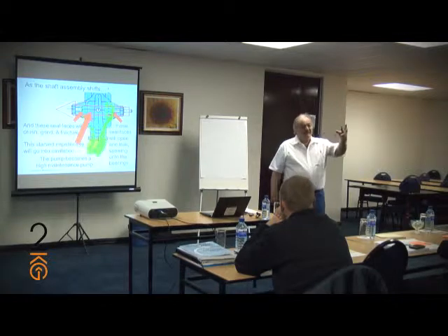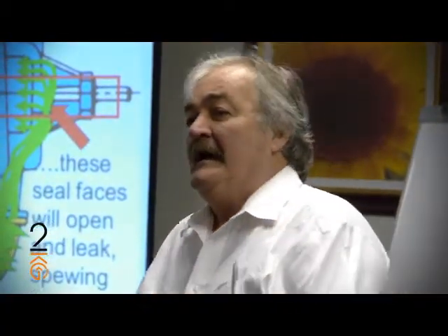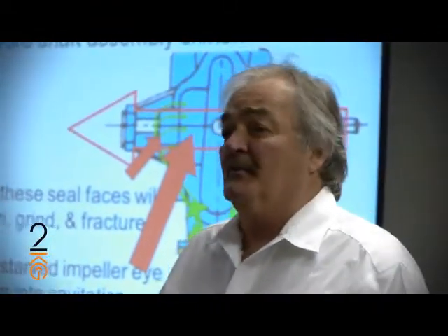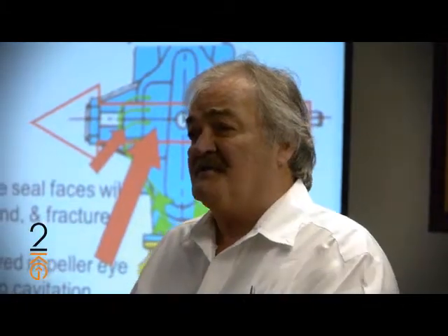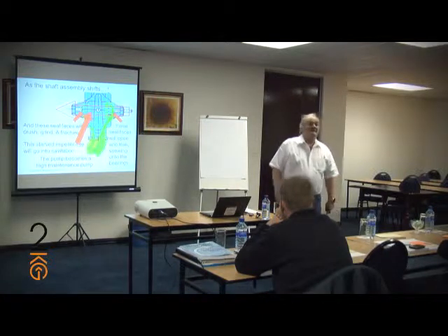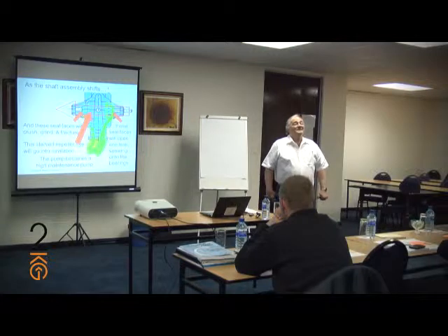I want everybody in this room to think about the pumps where you work. And then the question would be, do you have elbows on the suction nozzles of your pumps? I'll just leave that for you to think about. You'll also note that those are also the same pumps that are problematic pumps.